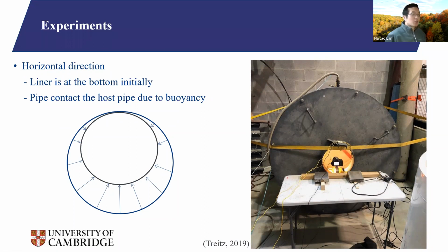At the beginning, of course, the pipe would touch the invert of the host pipe due to gravity. So when the water is pumped into this cell, the pipe will move up to touch the crown of the host pipe, or this cell, because of the buoyancy. So we have another situation to simulate the conditions in the field.